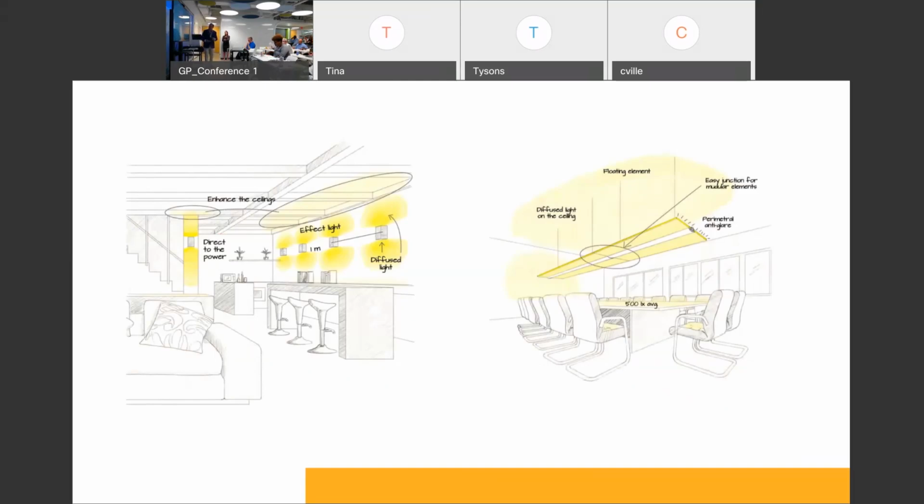Do a quick sketch. Then of course we have our horizontal luminance that's required, 500 lux, 50-foot candles, that's great. But do you really need it from a centerpiece?